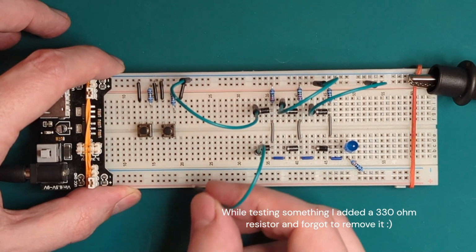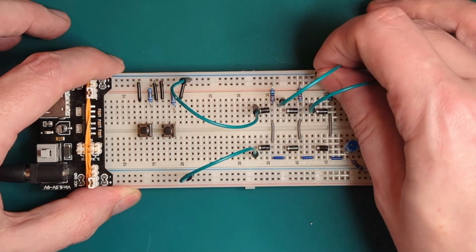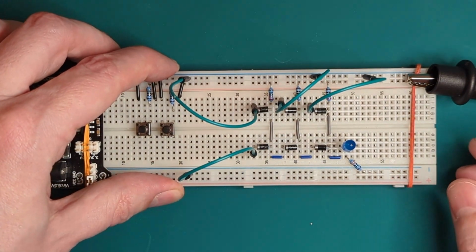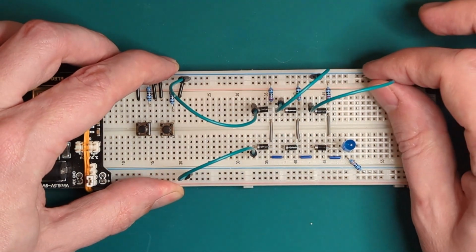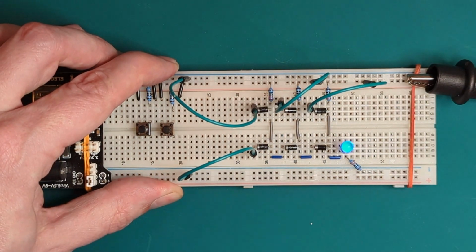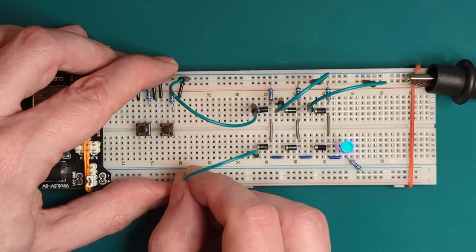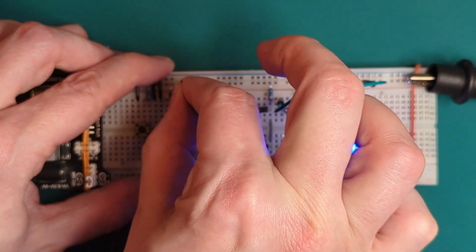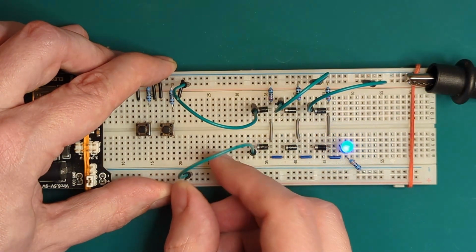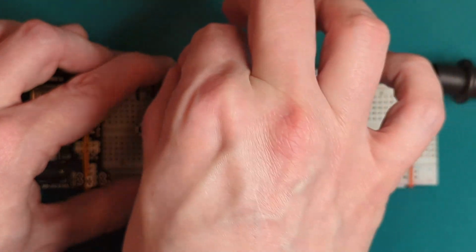Okay, so I rebuilt this and plugged this to everything to 0. Well, almost everything. So let's power this up. And it seems to be off. So unless I set everything to 5 volts, the LED should be off. However, you probably can see that it's glowing a little bit. So there's something off going on here. And of course, when I put everything in 5 volts, the LED lights up brightly. But in other cases, it kind of has this flicker, but it doesn't go fully away.